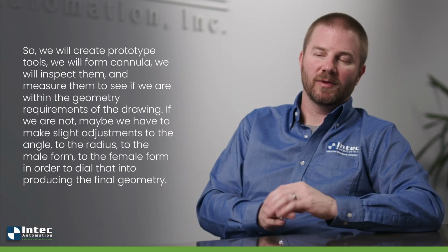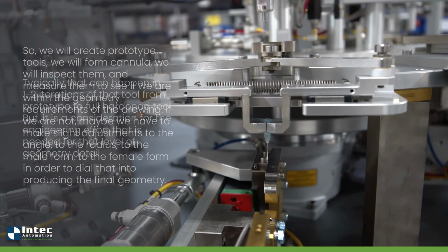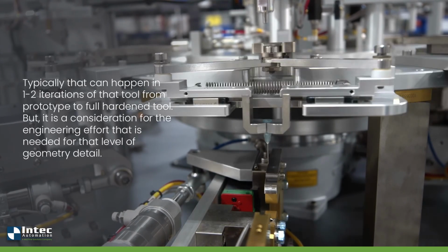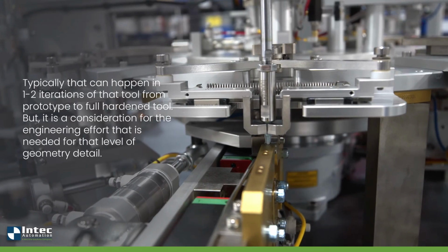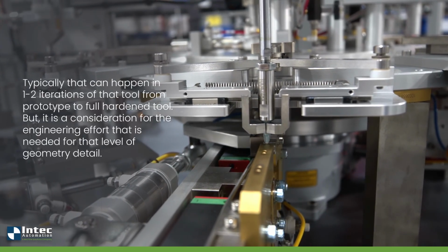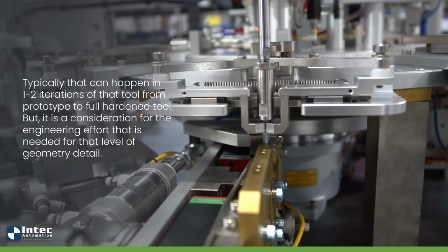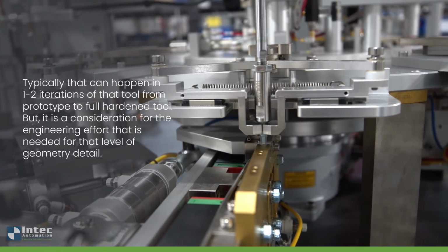If we're not, maybe we have to make slight adjustments to the angle, to the radius, to the male form, to the female form in order to dial that into producing the final geometry. So typically that can happen in 1 to 2 iterations of that tool, from prototype to full hardened tool. But it is a consideration for the engineering effort that is needed for that level of geometry detail.